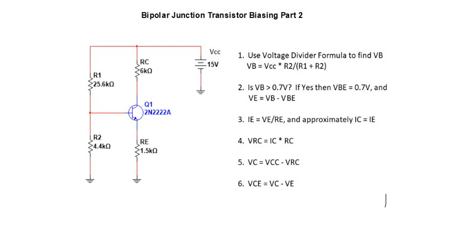Then we drew a diagonal line through those 2 points and said that, with that choice of VCC, RC, and RE, that was all the possible points that we could operate in.